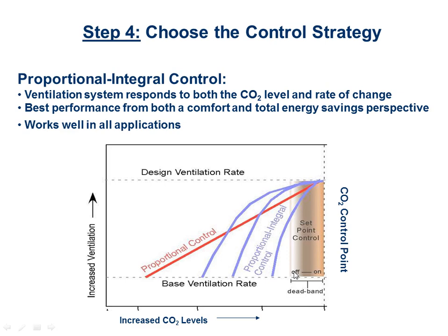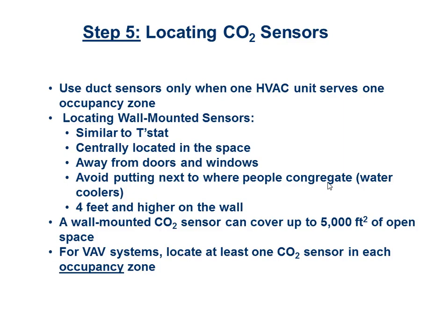Basically, a PID loop just predicts how fast or how slow I'm getting towards my set point, and adjusts accordingly. So this bronze colored thing over here would show me on-off control, boom, boom, boom, boom. The red would be my proportional control, and then my proportional integral derivative PID loop control would be one of these blue lines, which is a much smoother way of getting to where I'm trying to go in a much cleaner fashion. The set point control is pretty much old school. The proportional or PID loop is the more common way you'll see rooftop manufacturers doing it.